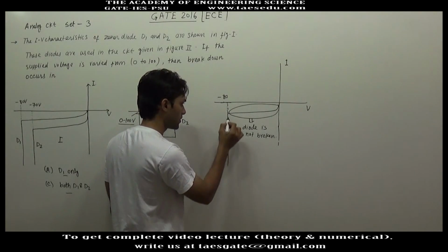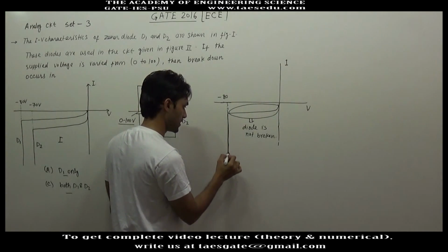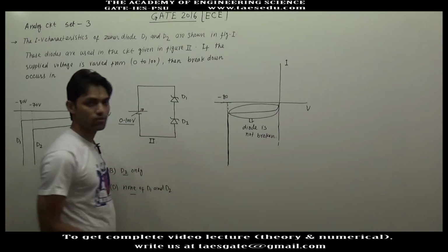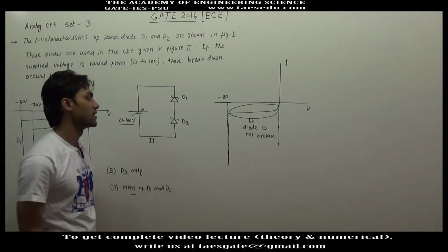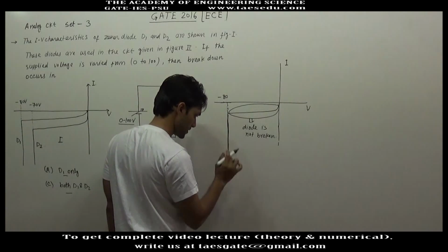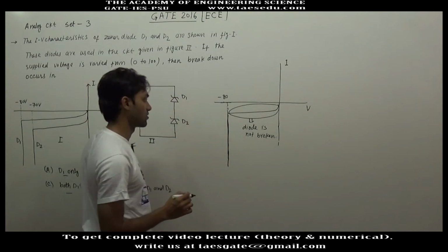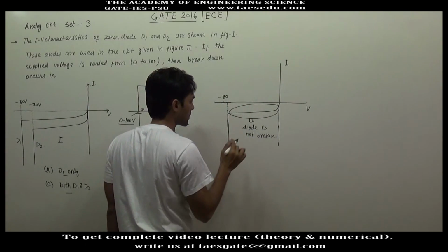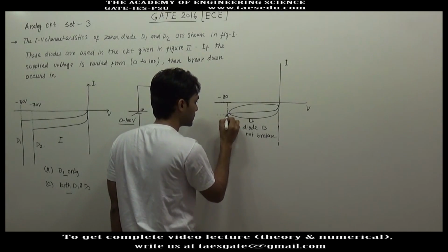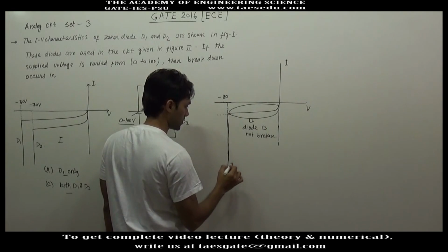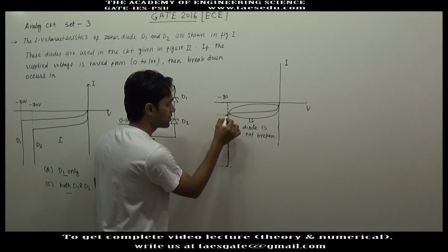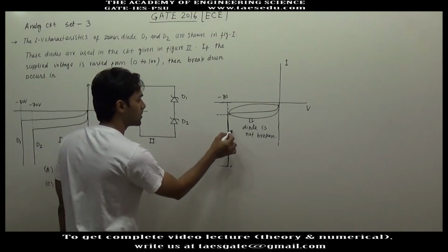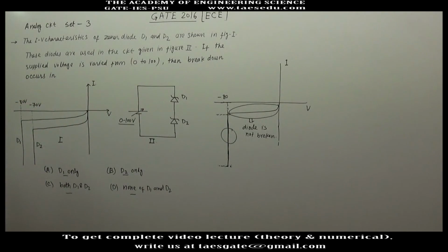and the current, normally we take this line as, or we think that the meaning of this line is if the diode is broken, the current through it will be very high. But this is a misinterpretation of this line. This line says that if the diode is broken, the value of current may be anything between this value to this value. The current can take any value between the starting to the end values. The value of current will depend upon the external circuit. It is not decided by the Zener diode.